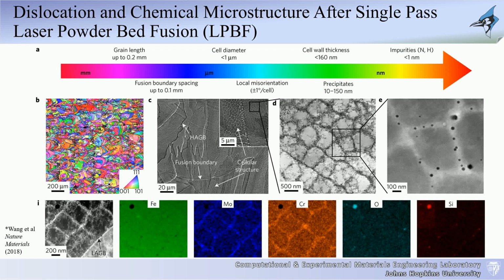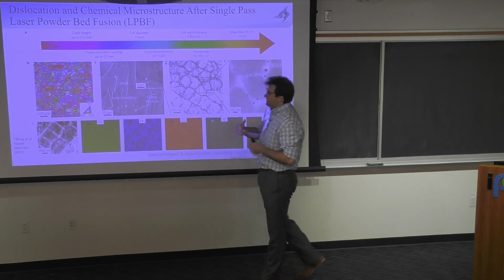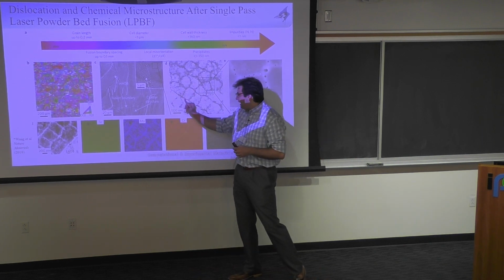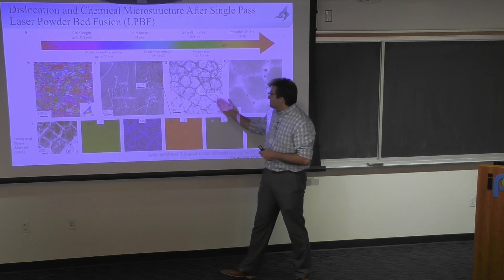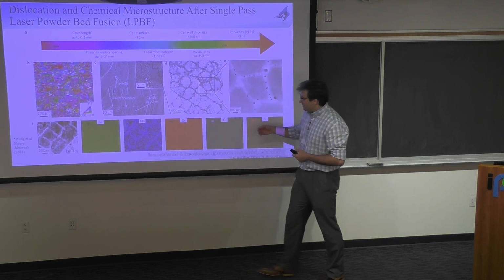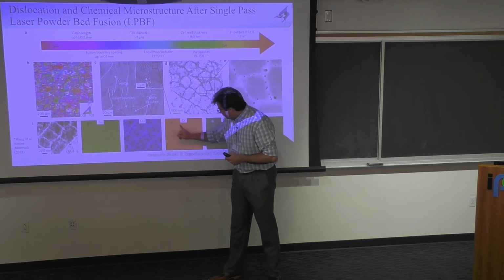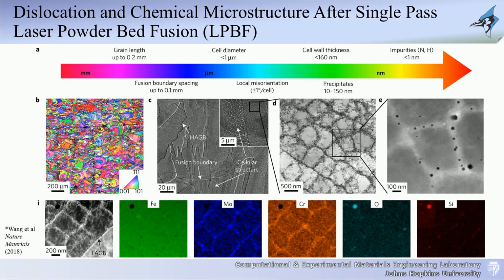So what they are actually seeing here that is different than conventional techniques is that if you look closely in the different grains, when they did these etching, they started creating these boundaries that are forming, and these boundaries align quite nicely with these high dislocation density regions. These high dislocation density regions seemingly are correlated directly with areas where, and unfortunately with the projector, there should be very clear cells right here that mimic these exactly, where you have high chrome and high molybdenum concentrations.